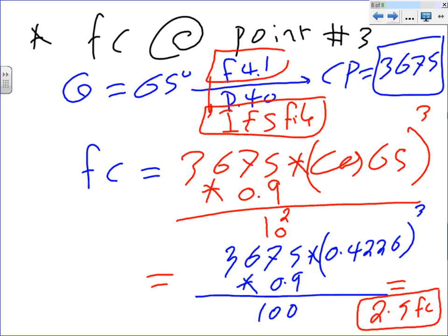Now, Ryan, if I want to torture you more, I would add another 16 points with another 16 angles and ask you to do the calculation over and over. Now the beauty about Visual, thank God, imagine they used to do it by hand before the computer. They used to do point-to-point calculations by hand, old-timers. Now you put in your fixture and all this mapping happens behind the scenes, and it does the calculation. Visual defaults to 2 by 2 feet.